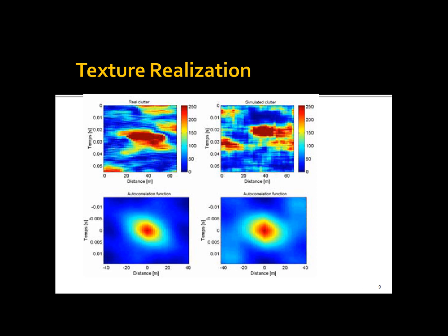The third is the chaotic model, which assumes that the processes involved in sea clutter generation are non-random but purely deterministic phenomena. This approach also requires a new radar processor paradigm. Results obtained from one of the prototypes of this model seem very promising, achieving perfect detection. More real data validation and noise robustness are required for credible validation.